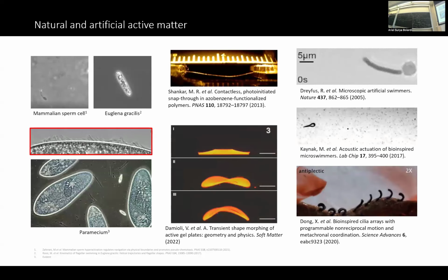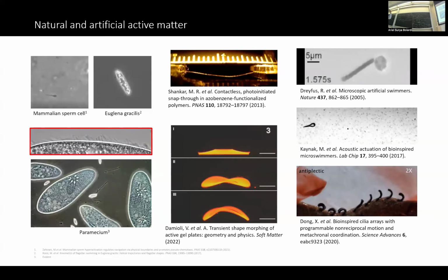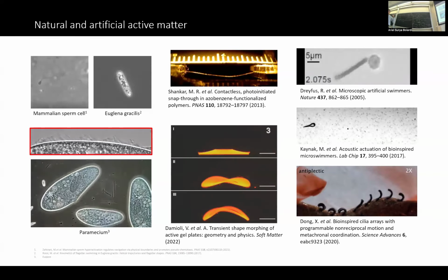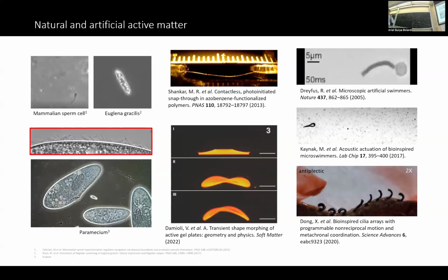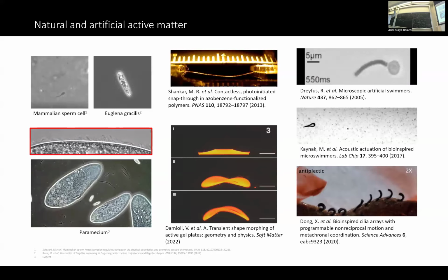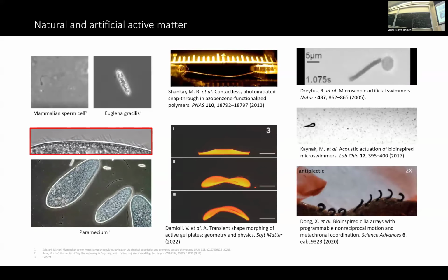It is quite natural to ask if these materials can be employed to replicate the motion of cells in biomimetic robots. This one is a seminal work, where there is a red blood cell to which they have attached a filament made of magnetic particles, attached to one another with DNA filaments. A magnetic field keeps the filament straight and a transverse magnetic field oscillates it, and this micro robot swims in this way.